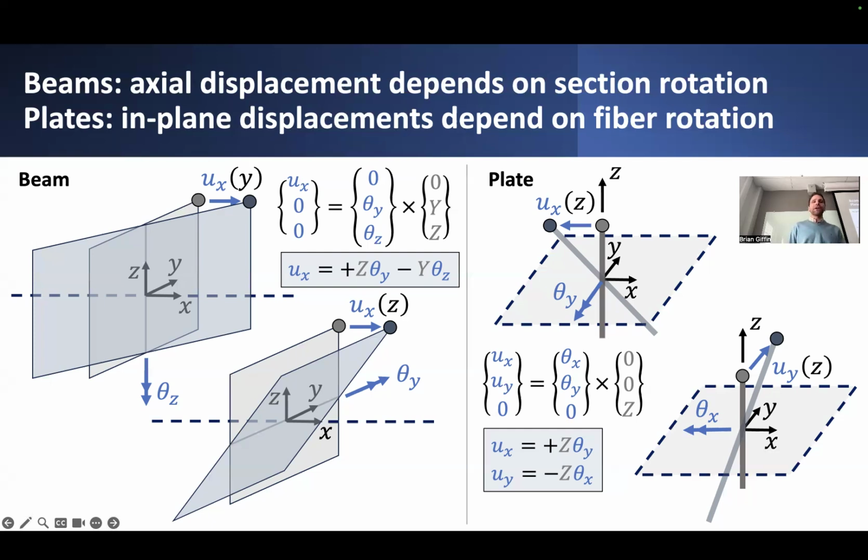Now, what I want you to look at is exactly what happens to individual points on this cross-section under these assumed rigid rotations of the cross-section as a whole, and specifically at the axial displacement of any point you want on this cross-section. I'll just look at the corner here.